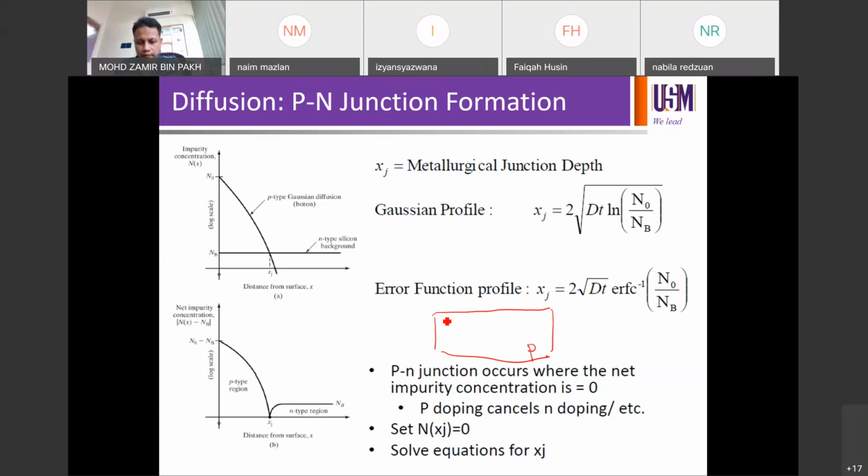To be able to determine the depth of the process after the diffusion, you can determine it by looking at the curve. So physically on the wafer, as the process goes on, you can also watch this on YouTube. They have uploaded about the diffusion last time. So this will be the depth, for example D, the depth of your emitter or of your channel or whatever. Channel, we call it on MOSFET.